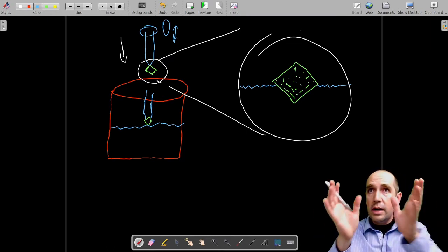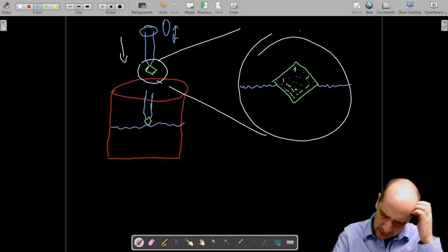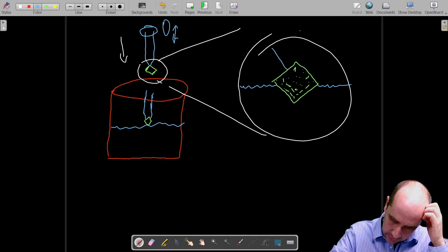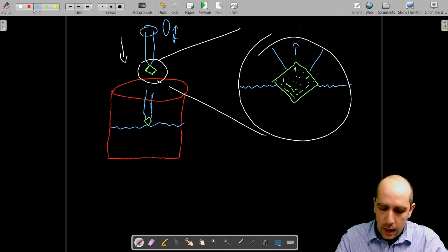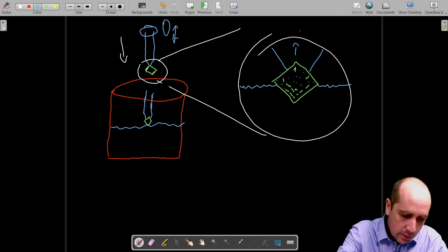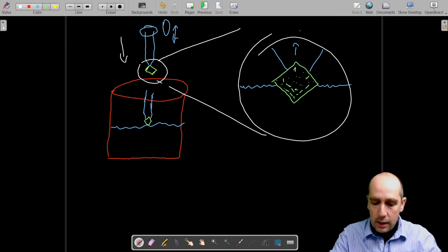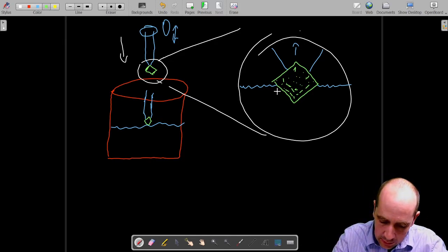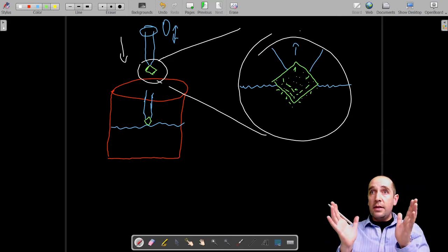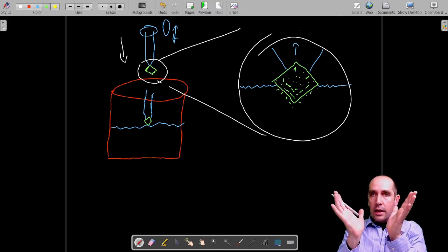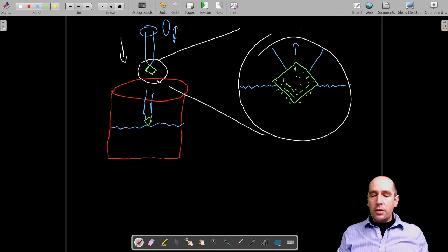The atoms that are really close to the walls of this silicon seed. So this is, again, the rod that can be pulled up and turned around. All the atoms that start lowering their temperature in the mold, in this liquid around the seed, start adhering to the surface of the silicon seed. Since this is at lower temperature, they adhere and solidify, but they solidify in such a way that they follow the same crystallographic orientation.